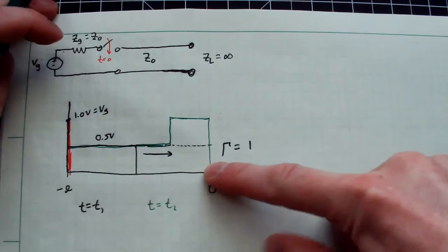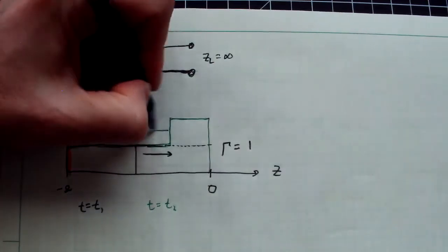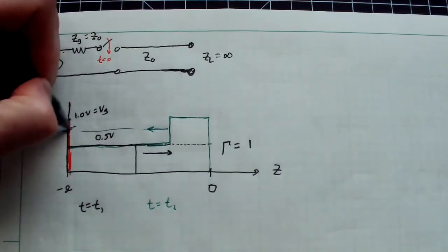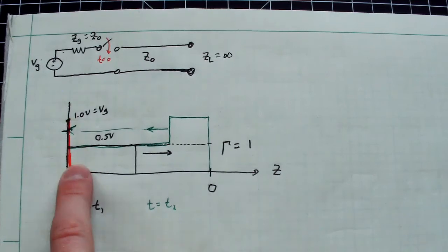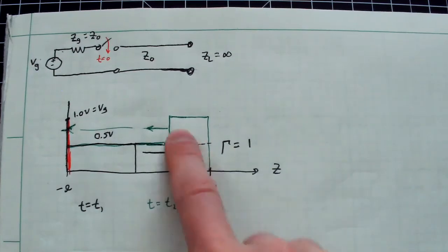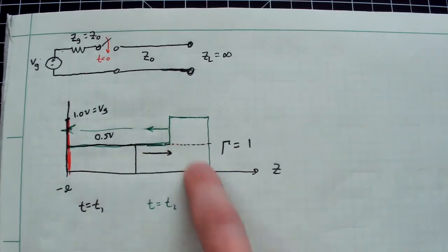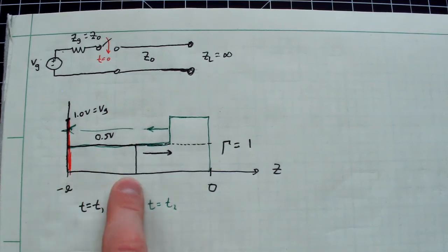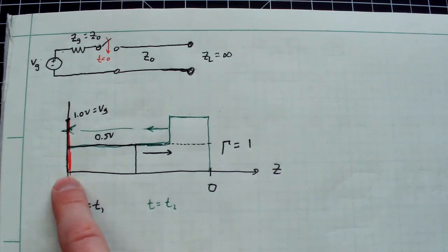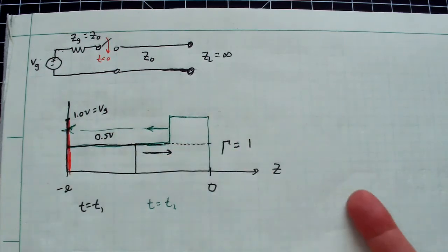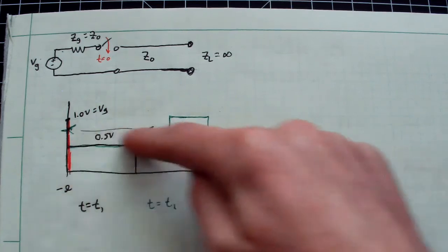So you would see it strike the open circuit, and then I get a reflection, which again propagates down at the phase velocity of the line until it finally strikes the generator here. But since the generator is matched, nothing happens. It'll just travel on through exactly like a matched load. And so that's another important concept: this wave doesn't really care whether it's hitting a generator or a load. All it sees is some equivalent impedance change between the characteristic impedance of the line and some resistor that is striking here. And since they're matched, it will be like a matched load. But hypothetically, it could be not matched, in which case it would go down, bounce back again, and so on.